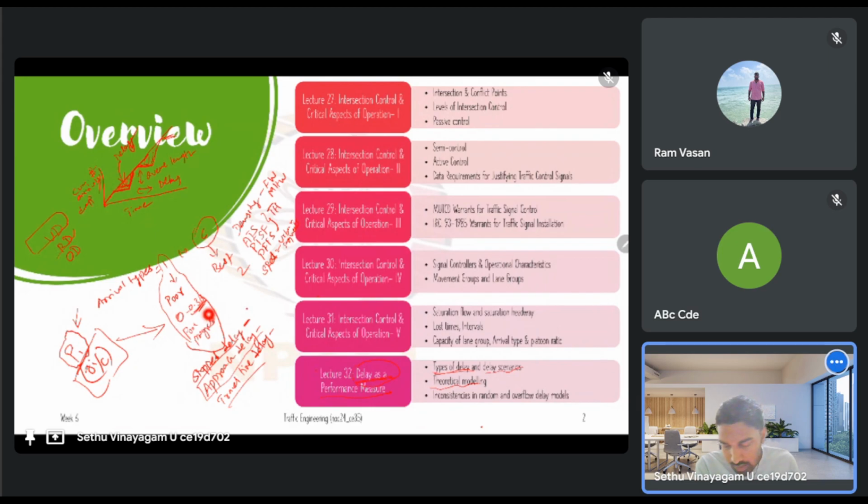Then we have the random delay. Sometimes in some random cycles we'll have higher demand, right? Mostly it will be uniform, but in some random cycles, the delay will be higher. So it may not always catch up with the arrival curve, right? There may be some spillback into the following cycle. That happens randomly at different cycles. So that is the random delay.